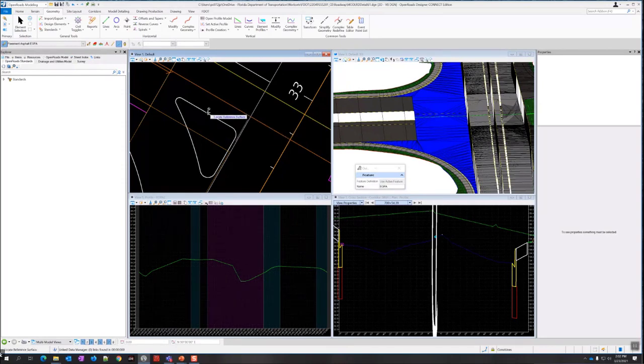And then it asks me to locate the reference surface. So now I can come over into 3D view and select one of the triangles. Use active feature, pavement asphalt UPA, that's fine. I select that. So it says locate reference surface or reset to end. So I already selected it, so I'm going to reset. And it created this profile here.